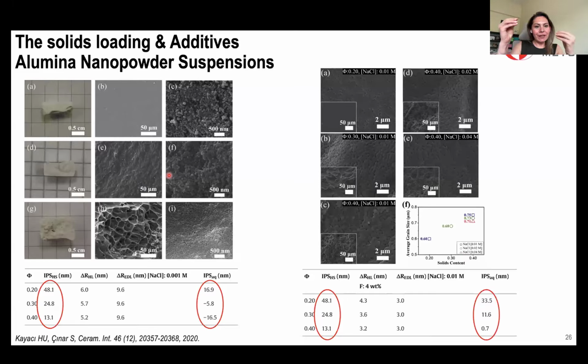So that makes sense to me because during slip casting, the particles consolidate, right? If they do not have enough free space, they're just going to settle down wherever they find, rather than trying to find the most energetically favorable spots for better packing. So here we lose those packing properties.